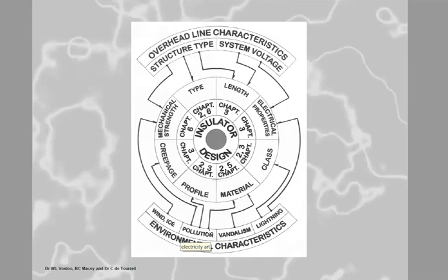Now when hydrophobicity transfer takes place, it goes into the material, the pollution, okay? And what happens to A? It becomes smaller, smaller, smaller until it nearly disappears. And that's why current goes down. And rho is the resistivity of the pollution layer. As it migrates into the pollution layer, what happens to rho? It becomes bigger, bigger, bigger, bigger rho, bigger R, smaller I. Insulator pollution, explained, done. Rho L over A. I can solve any in-service problem you've got with pollution with R equals rho L over A. And that's it. So simple as that.